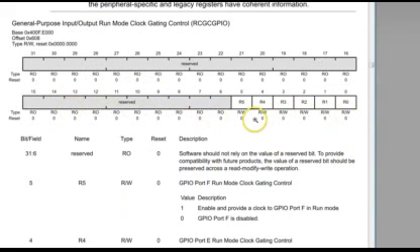The register is shown as a block of bits, always numbered from 0. The type of each bit is indicated, whereas RO means read-only, RW means read-write, and WO would mean write-only. The logically related groups of bits are documented below the register block picture, starting from the most significant bit. For you, the most interesting is the description of bit 5, because this bit enables the clock to GPIO port F. This confirms that this register is exactly what you've been looking for.